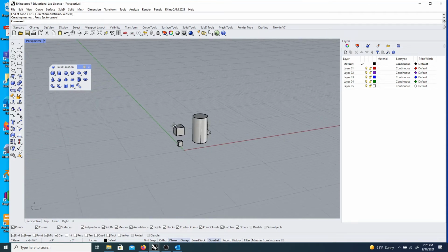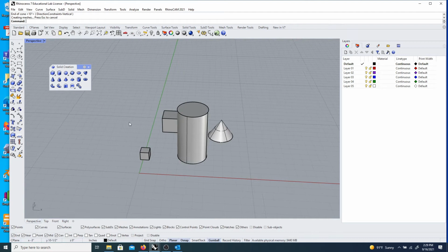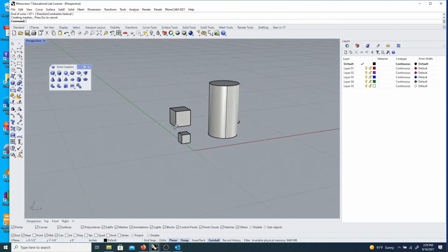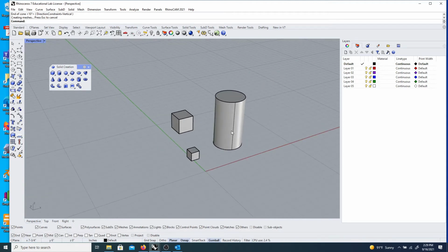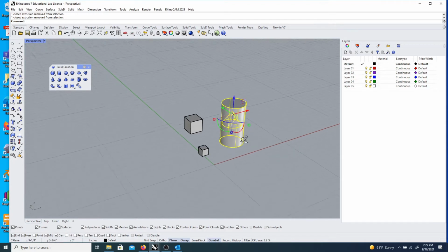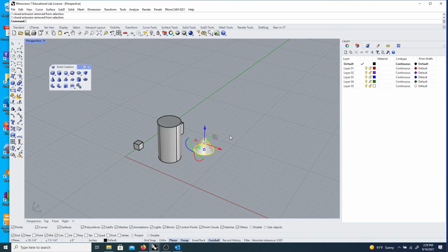And it's really useful to know how to move around within this space. So you can see me rotating here. The right mouse button allows us to rotate. The left mouse button allows us to select. If we've selected a bunch of stuff and we don't want some things, you can hit Control and click on what you don't want. I once looked up the most used shortcut in Rhino, and it's Control left click, deselect.